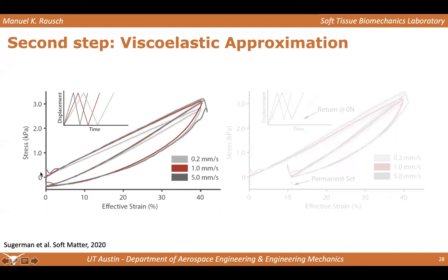And of course, here you have your native loading curve, and then you have your unloading, and then you have your reloading, right? And so one thing you find is that you have some sort of stress softening. You don't return on the same curve. You also have hysteresis. And you have this interesting effect where when you return to your 0 point, you have negative stresses here.